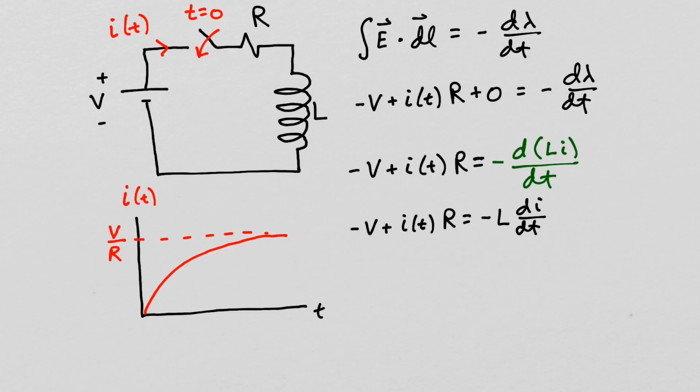This equation should look familiar to you, which previously you would obtain using Kirchhoff's voltage law, and this term as the voltage associated with the inductor. But if the voltage is really the integral of E dot dl through the inductor, and the inductor has a negligible electric field in it, the voltage obtained by integrating E dot dl is really 0. This term really comes from Faraday's law and the change in flux linkage with respect to time associated with the inductor.